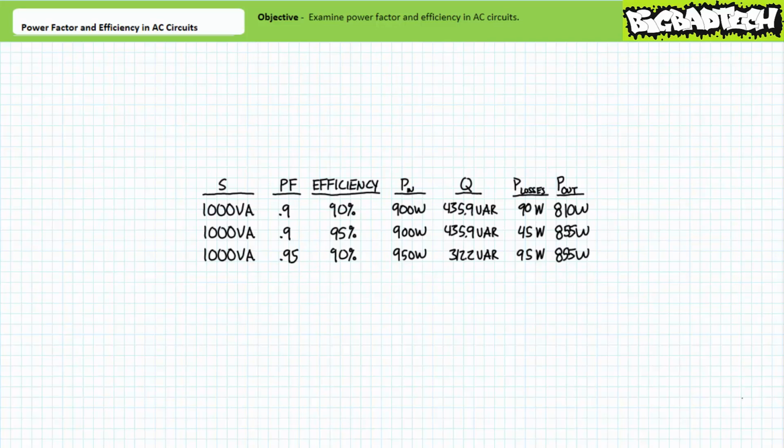This implies that the third implementation might require a more robust, i.e. heavier and more expensive frame or heat exchanger to dissipate these increased losses. Again, all power has to go somewhere, even if its destination is considered a loss. One cannot expect even a 99.9% efficient gearbox designed to handle 2 megawatts of power to be made out of tissue paper and compressed cheese.